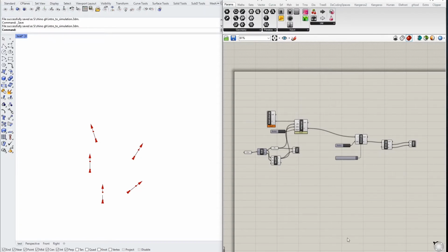We will begin with the Grasshopper definition created in part 1 in this video series to move 5 Boids over time. Similar to part 2, we will insert additional processes between the node creating the Boid instances and the node to run the move function within each Boid.